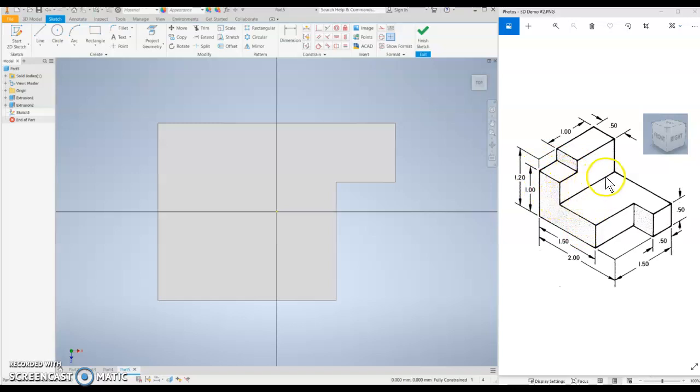So we're going to draw a rectangle that's going to be basically the whole distance across here. So we know that it's 1.5 is our depth and our width is 0.5. So let's go draw a rectangle. You can choose to either do the bottom corner or the top corner here. I guess we'll choose top for me. Now it's first prompting for the width. We can see that that is 0.5, so we'll type in 0.5 and then hit tab over, and then our length we can see we can either snap it down or we can type in the 1.5 to get that full distance. Okay, we've drawn our rectangle in our 2D sketch.